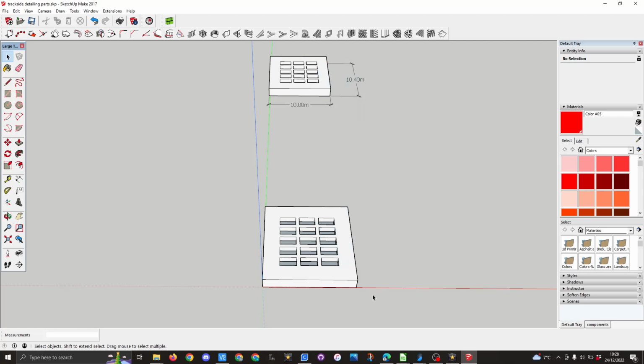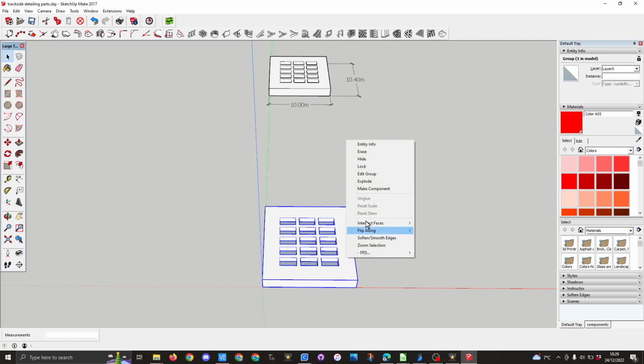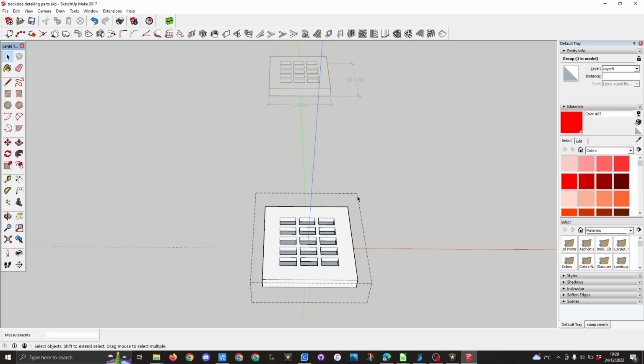We have one thing left we need to do. We need to remove the glass from the window frame. To do this, we first click on it. So this has now been made into a group. We need to edit the group, and we need to then click on the glass pane. So just here, single click and then press delete. This now is ready for us to be able to send it to our printer.